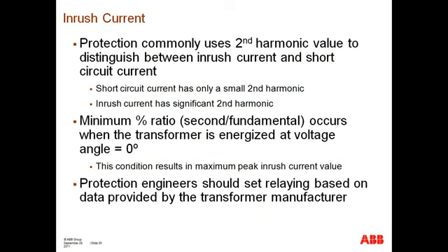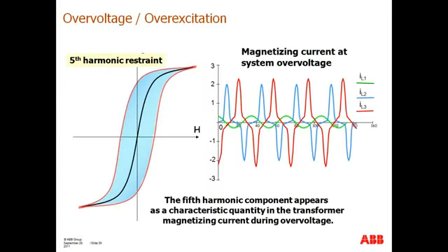The higher the setting that you select, the more likely you are to operate during an inrush condition whose second harmonic level was not high enough to be identified.